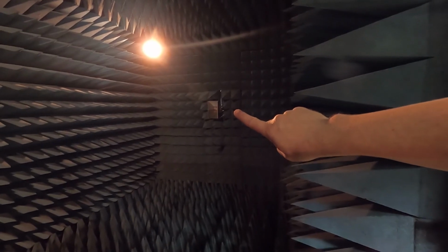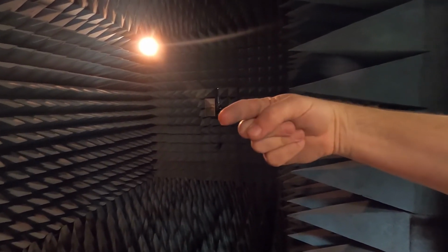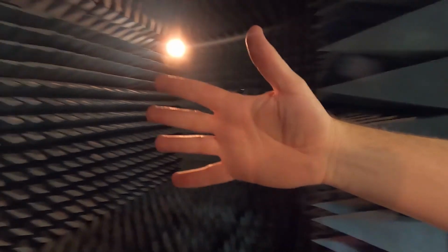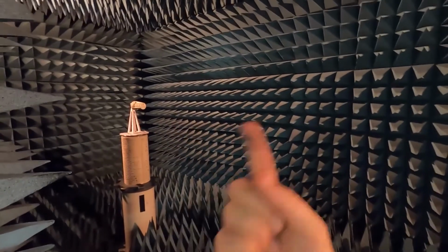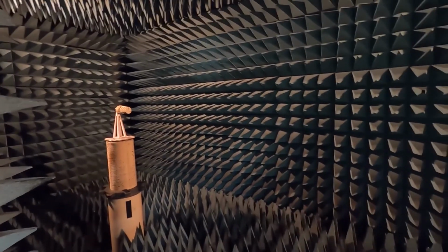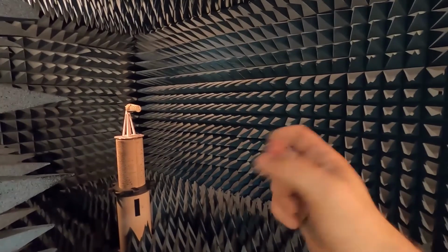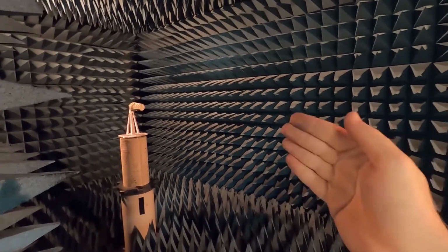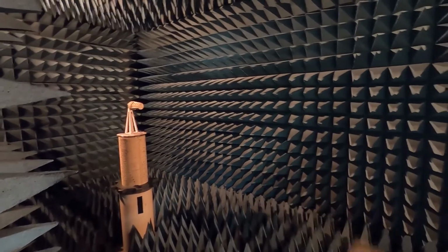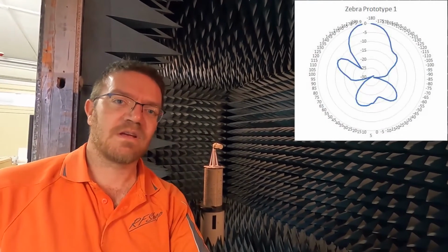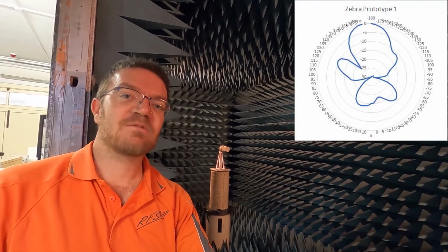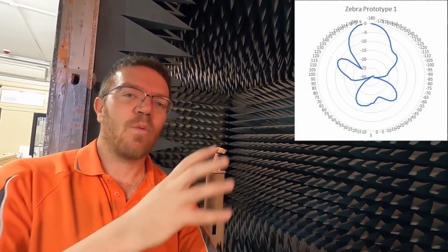It's a wideband horn antenna that sends a signal. So the signal comes here, you see waves coming through, travels all the way here, gets received there. By turning this antenna around, you take a measurement, turn a little bit, do another measurement, turn a little bit again, do another measurement. That procedure, which takes about 3, 4, up to 5 minutes because you go through all the steps, builds you a radiation pattern. The radiation pattern is then what we use to understand where this antenna works.